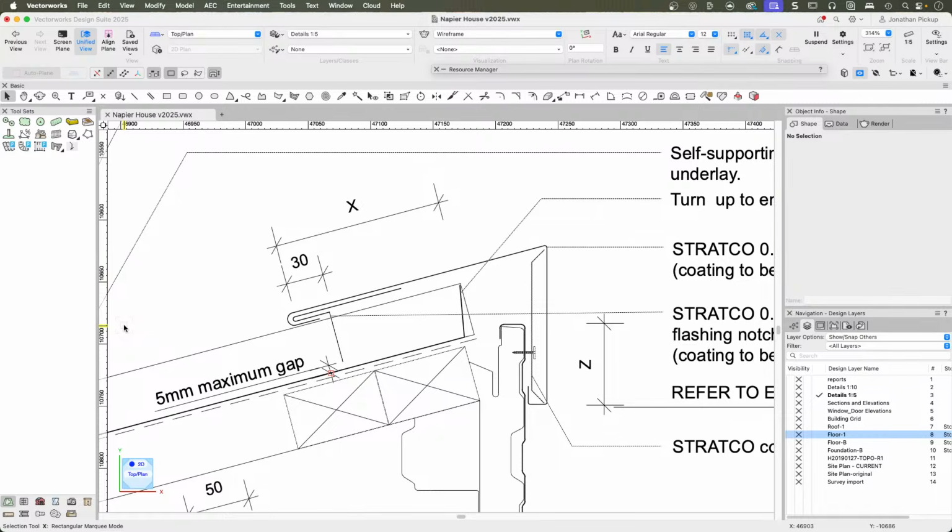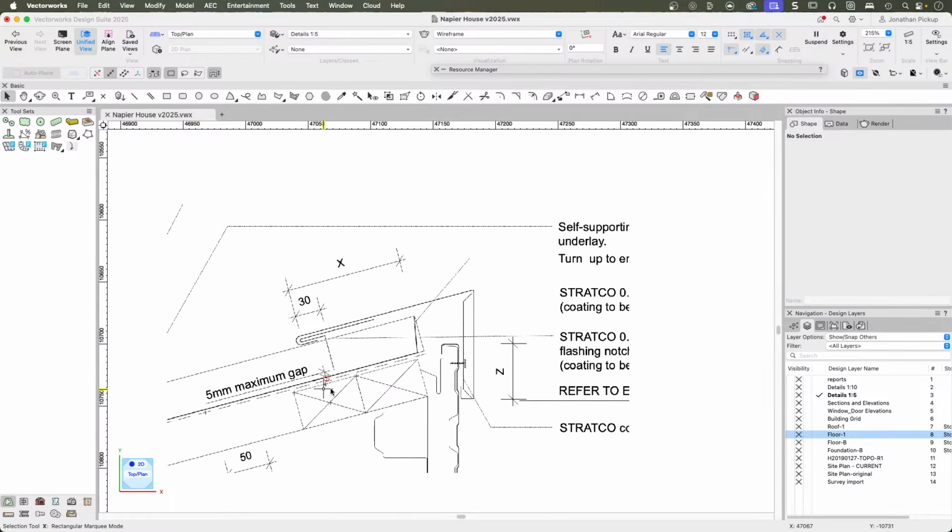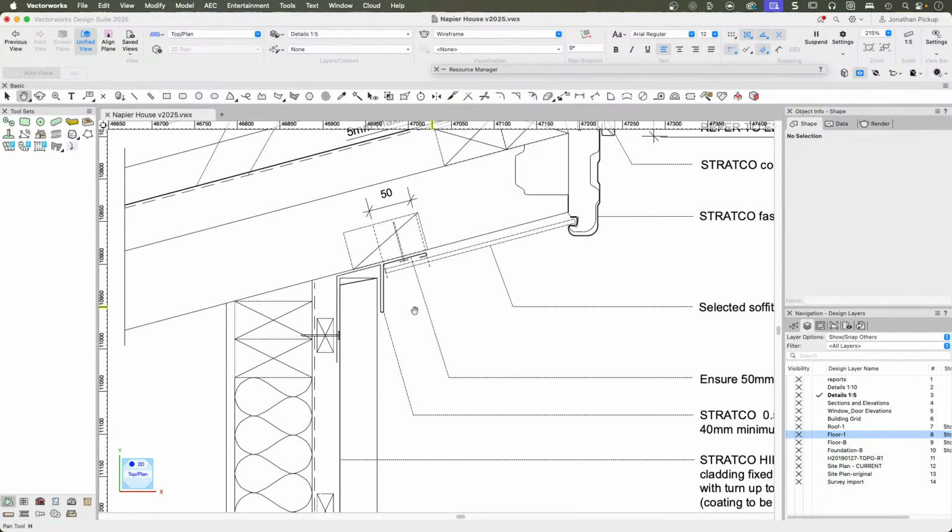So number 1, deflection. Now if that doesn't work, for example, if that fails somehow, I've got a drained cavity. So if any water gets through here, I've now got a drained cavity to keep the water away from my building. So I've got deflection, and drainage is my backup plan. Drying is the next one. Drying is great. So for example, concrete block, bricks, those kinds of things dry after the sun comes out. So they might get wet to start with, but eventually they will dry.